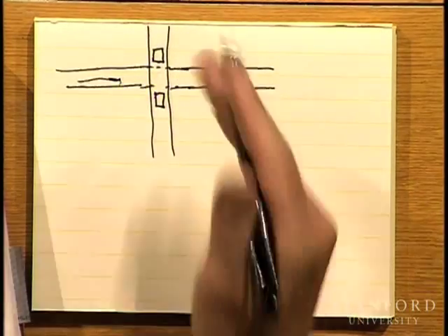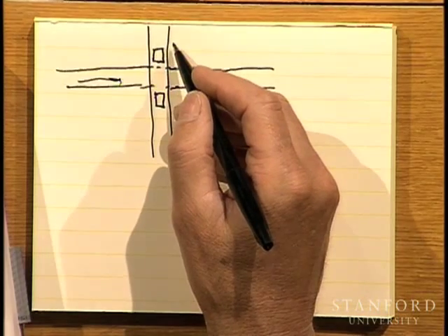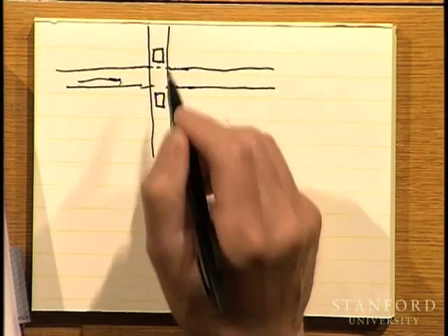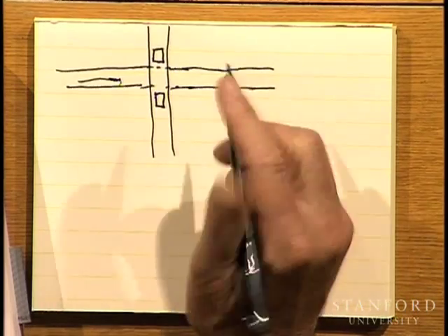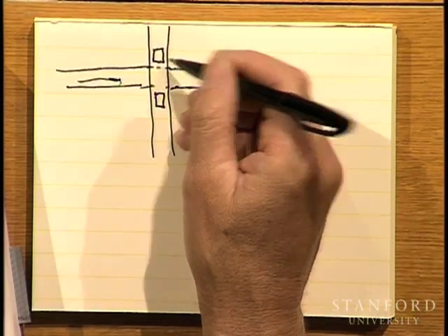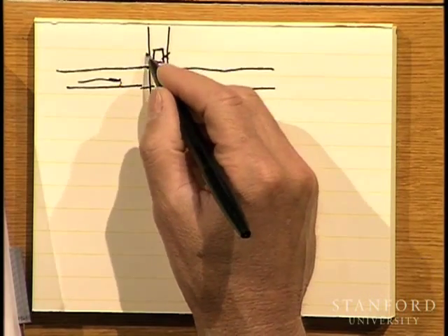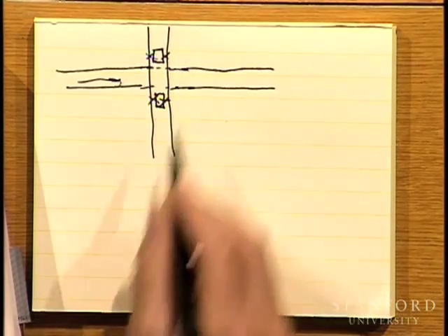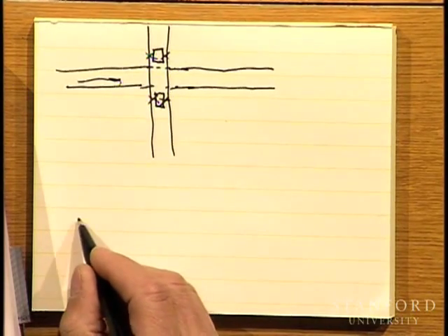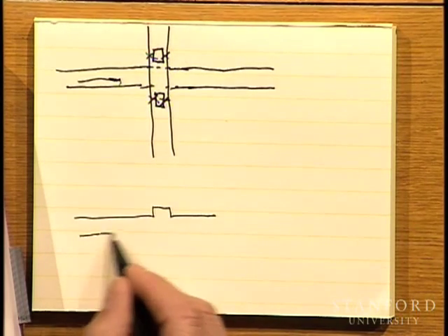And then when I cut the bottom metal, we use a wet chemical process to etch the metal. We continue to etch beyond when it's 100 or 50 nanometers thick, until I cut it sideways or undercut it, removing the material underneath these thin regions. Then the bottom metal comes out looking like this, maybe with a little stub sticking out the side.